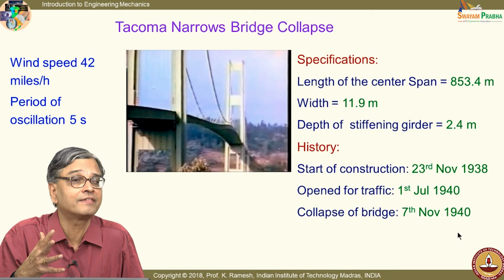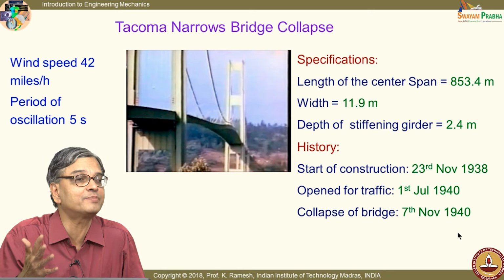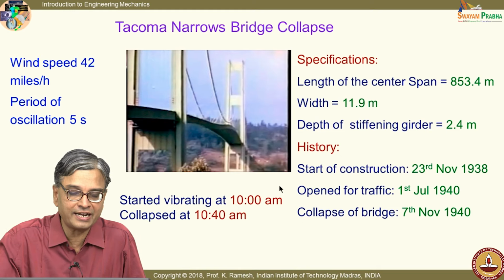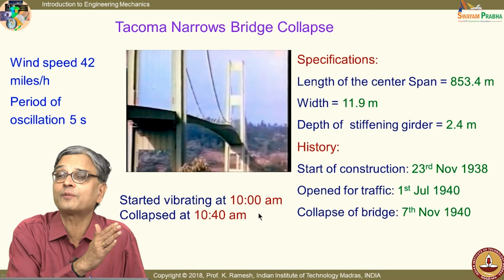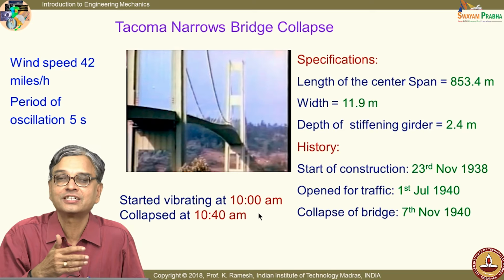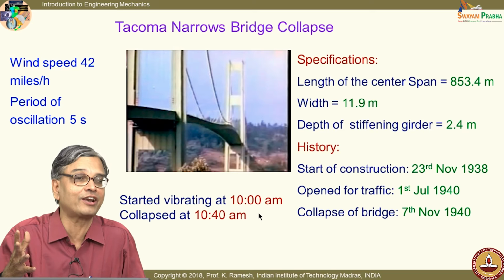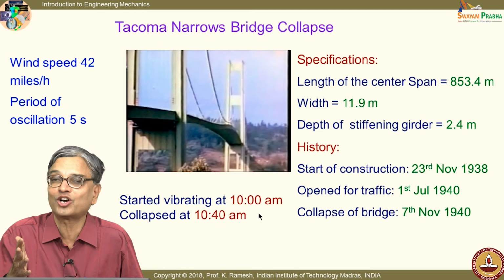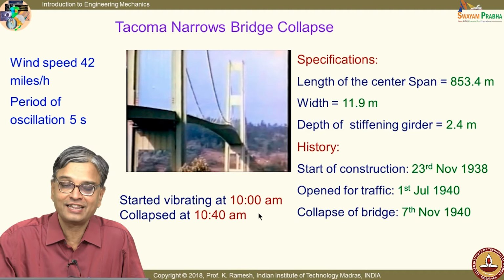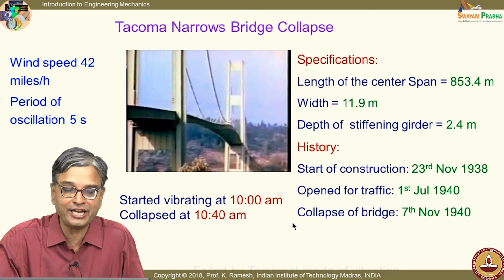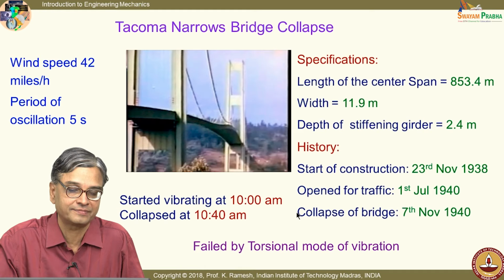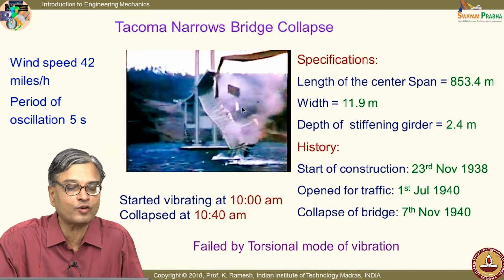What is it that they had not noticed while designing this bridge? And the interesting story is, it started vibrating at 10 o'clock in the morning and continued for about 40 minutes. There was a video store at the end of the bridge and he saw something happening and he started recording it. You might think that the video quality is not good, but you should also associate with time. In 1940, that is the quality that they had, and that is a real learning experience for many to see, and this failed by torsional mode of vibration, and the bridge completely collapsed into the water body.